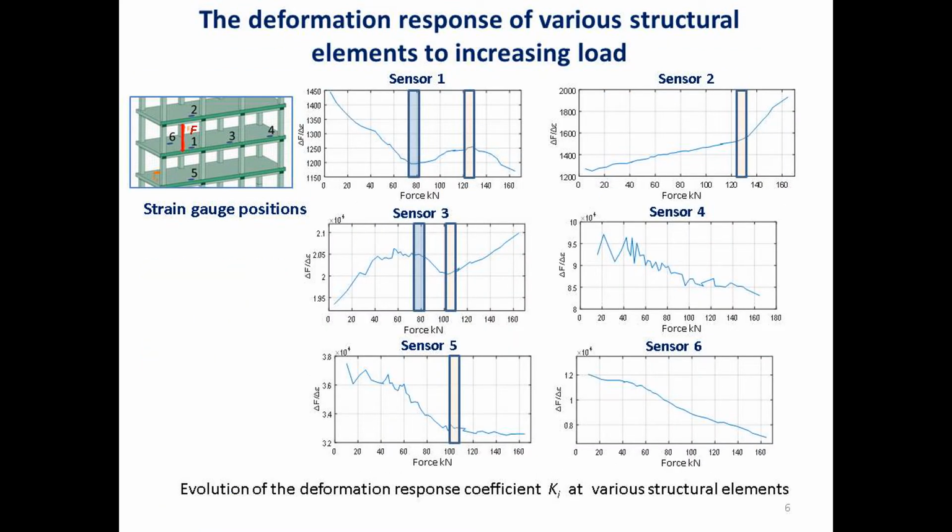These diagrams show changes in the deformation response coefficient when the static load increases from 0 to 160 kilonewtons. The curves obtained at various sensors look different, but we are interested in the graphs related to the points near the jack, sensors number 1, 2 and 3.